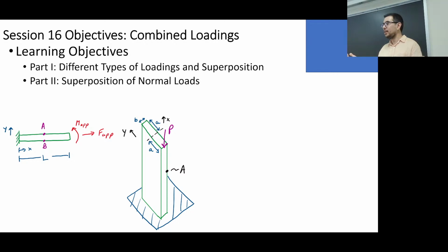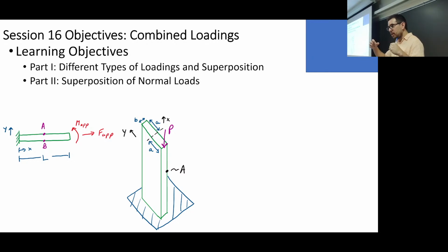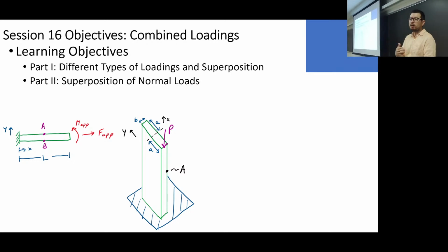Why do you think? So it increases the stress. Well, let's say I've got internal pressure, and then I push on the outside, inward. That axial stress, I could maybe get it to go to 0, because it's in tension from the pressure, but now I'm compressing it. At least in that direction, I've still got hoop. It's not helping with the hoop stress, but I'm decreasing the axial stress.